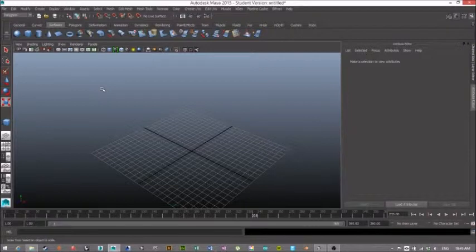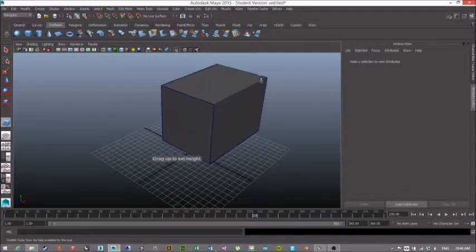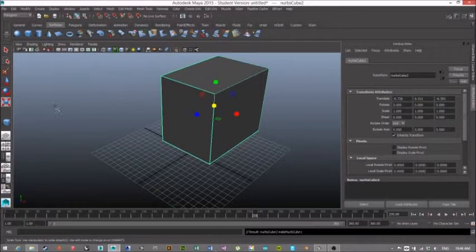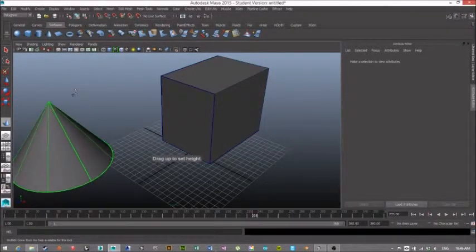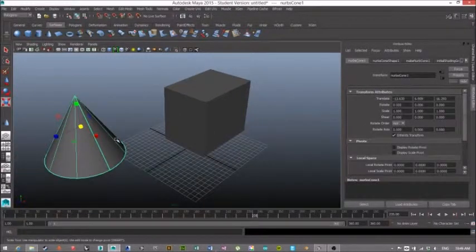You just kind of have to think about scaling stuff down. So you scale it, if you want it to be invisible, instead of actually trying to make it show, which is a little more complex. It seems like it'd be really easy to show geometry like that, but if you just take your geometry and you scale it to 0.001 in all the dimensions, it's not going to show up. We won't see it on the render, and so you just keyframe that along as you want. So let's actually go through that. We've got this geometry, and we've got a cone. Okay, so we don't want the cone to be visible until frame 50.